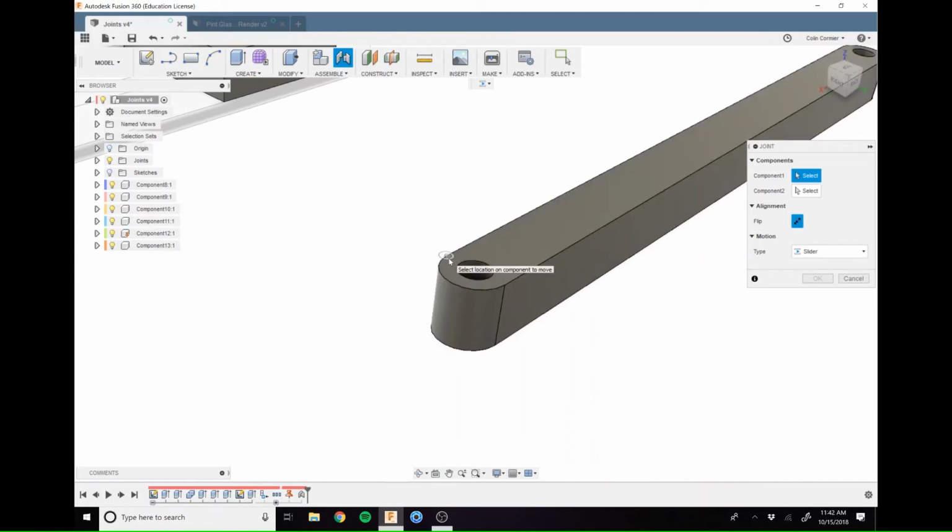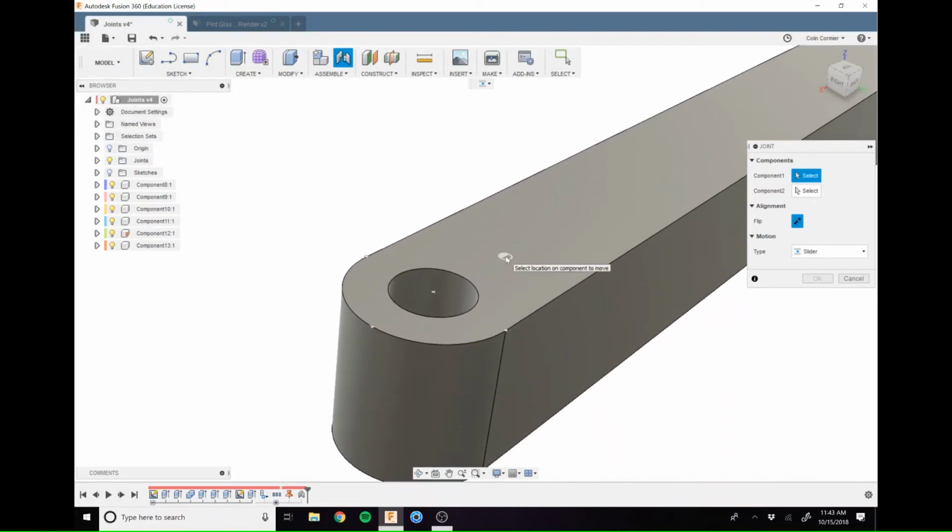Can you see this little biscuit or puck, or whatever shape this is? This is your orientation marker. Something important to keep in mind is that as I hover over these key points, my orientation marker is going to change. As I change over these faces and over these edges, the orientation changes. What's always going to happen is that I'm going to select one disc on this component and one on the other component, and the discs always match up face to face. And there's a little open-mouth smiley face, a half circle within there, that they'll always meet up opposite of each other.